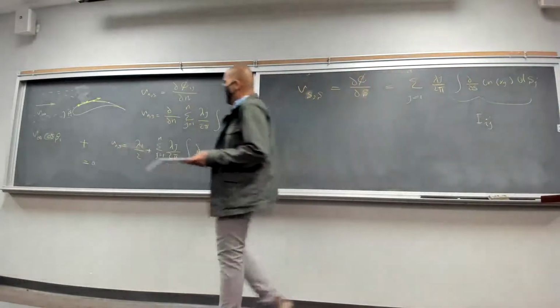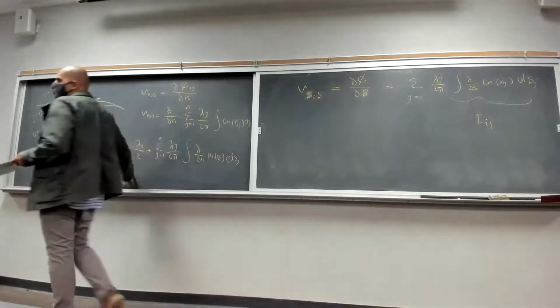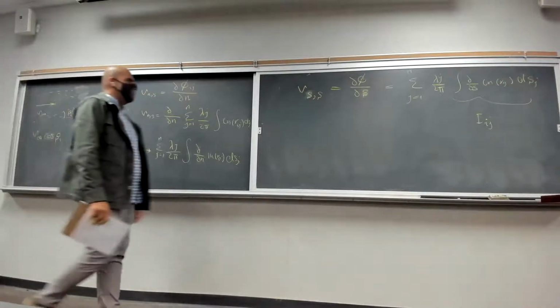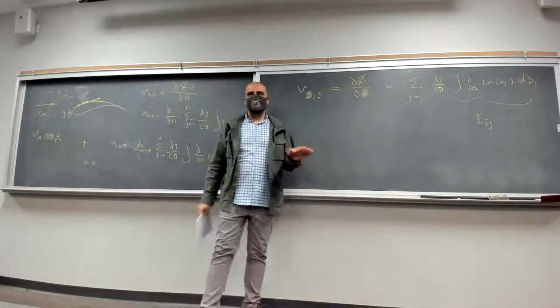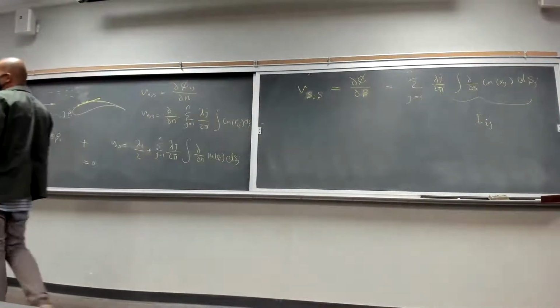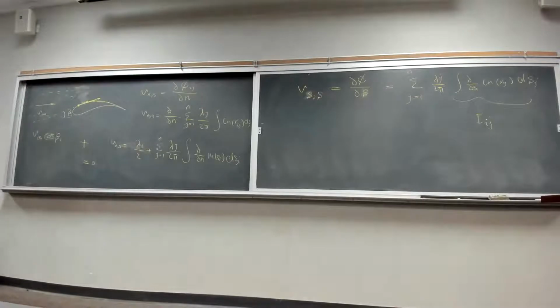So you find the lambda through this system of equations and unknowns, just linear algebraic equations, and then you find the velocity that is tangential to your panel. That was the idea of the inviscid incompressible flow. You only have tangential velocity, right? Okay.